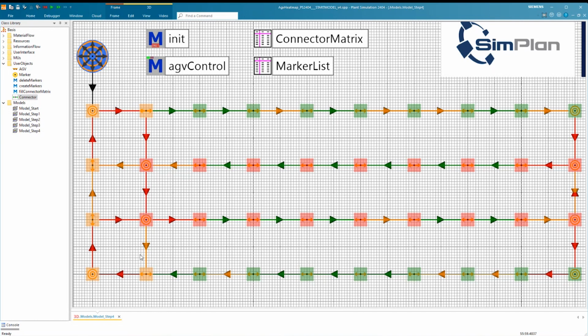Yeah, right. So I think that's everything from my side. What I wanted to show you: collecting some statistics for the markers, collecting statistics between markers, utilizing the connectors in Plant Simulation, and then painting this with colors in the layout to quickly visualize what areas are green, what areas are red. So where do we maybe have to take a closer look and add additional routes or add additional parking positions in between, or whatever options you have to improve the layout.